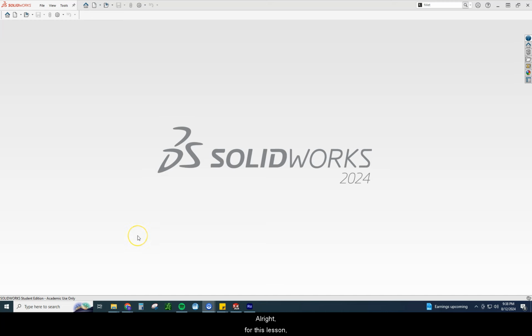All right, for this lesson, I really wanted to focus on a tool that we're going to be using in one of your first projects, which is the Revolve tool. We call it Revolve Boss Base. It allows you to create a three-dimensional object around a center point. So let's dive into that. First, I'm going to show you what it looks like, and then I'll be able to explain it a little easier as we get going.